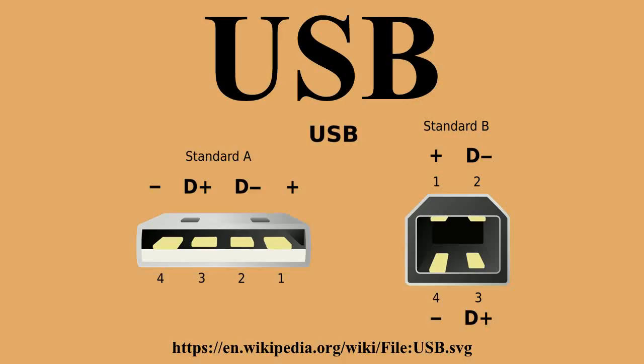The micro connectors were designed with frequent charging of portable devices in mind, to have a design life of 10,000 cycles, and also place the flexible contacts, which wear out sooner, on the easily replaced cable, while the more durable rigid contacts are located in the receptacles. Likewise, the springy component of the retention mechanism, parts that provide required gripping force, were also moved into plugs on the cable side.